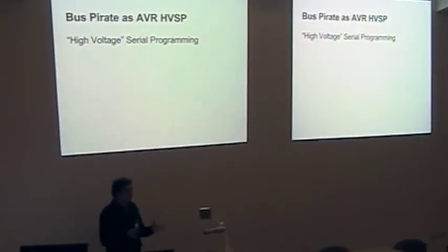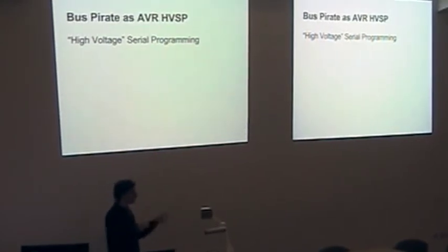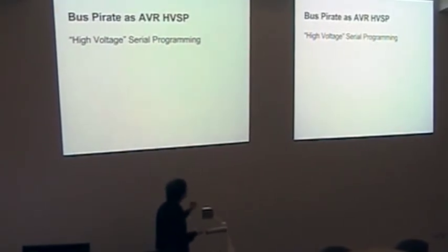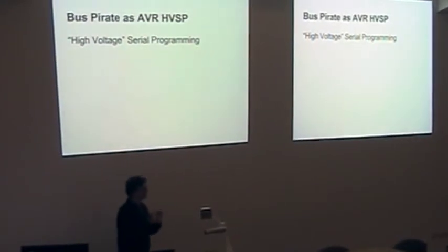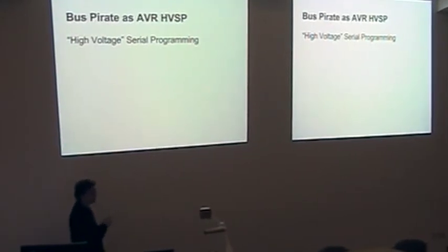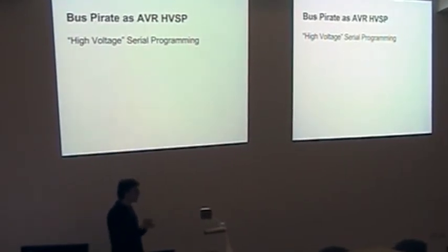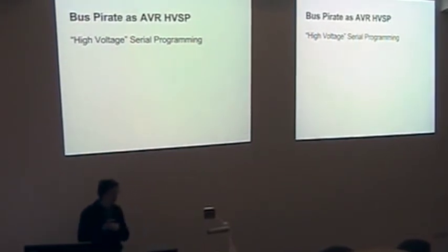Which is normally fine if you've got one of the huge, say, 64-pin monster chips. You just have this reset pin and it's all fine. But I'm doing a lot of work with the really, really tiny 8-pin AVR chips. So when you've only got 8 pins, you've got two power pins, and that's 6 remaining. Well, that's really 5 if you need a reset pin to program it.